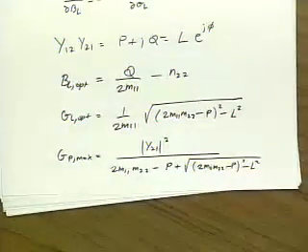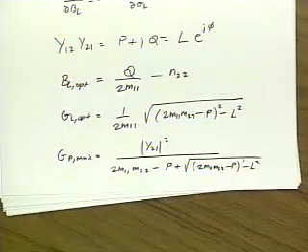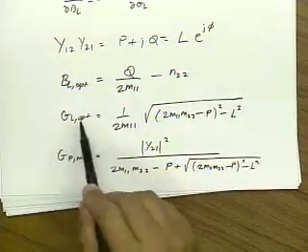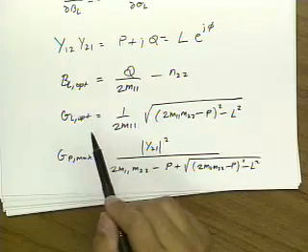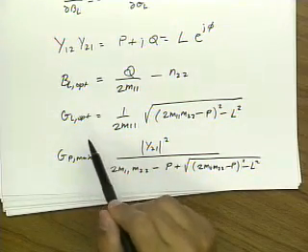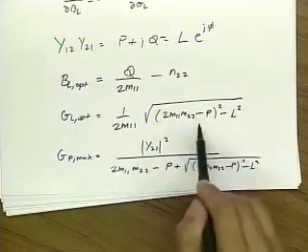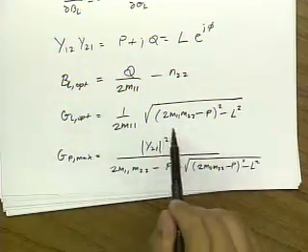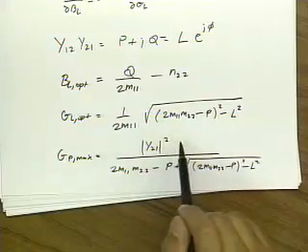Now, don't copy this down. The important thing is to notice that this is a conductance, so it has to be positive. Negative conductance doesn't exist physically, at least not as a passive termination. So for this to exist, this term has to be bigger than this term, and that's exactly the condition we talked about earlier under which a solution exists.